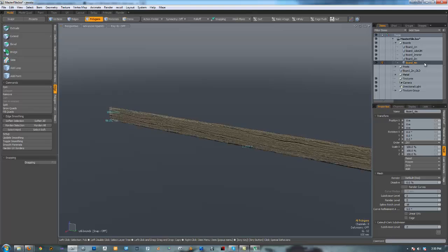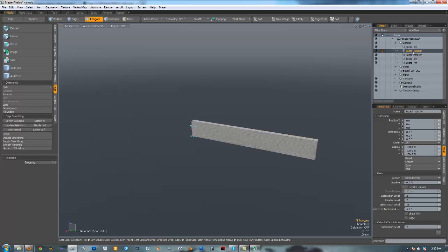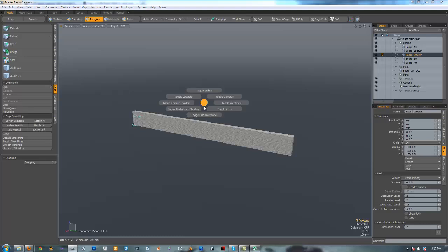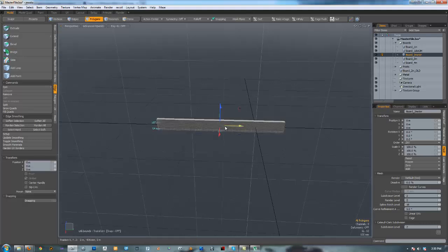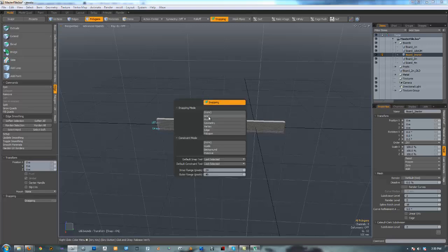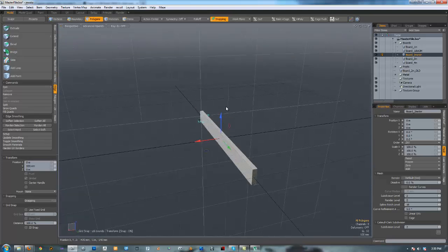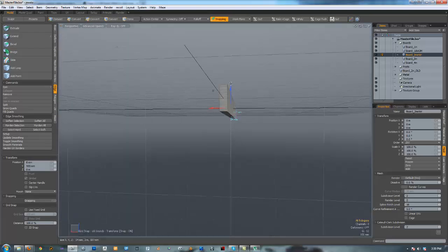So now if we cycle through, we can see that these are all kind of similar shape and size. Let's make sure that it is centered, which it is not, so we'll go board 2 meters. Turn on snapping by hitting X, hit F11 to bring up the options, select grid, and we'll just snap it into the center here, make sure it's right up top there.